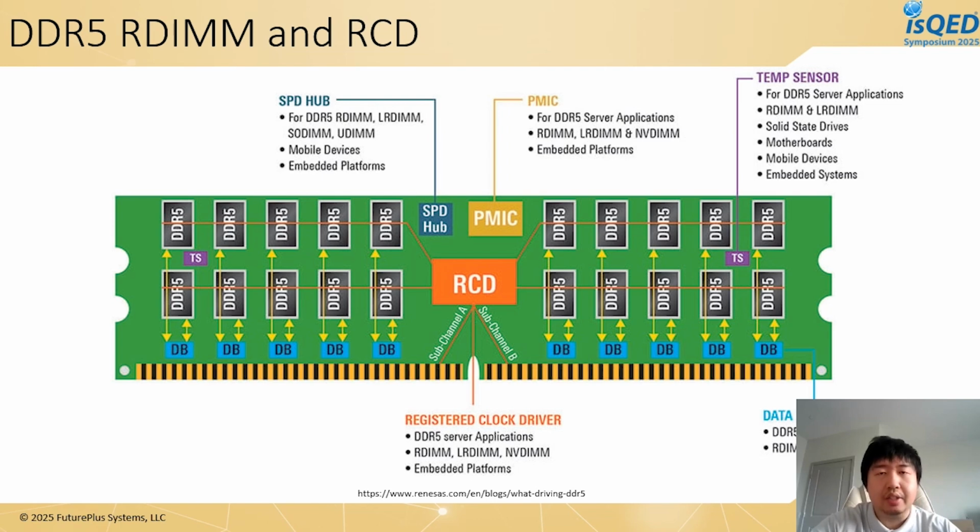So here is a block diagram for DDR5 RDIMM. Again, notice we have this RCD component on the center of the DIMM. Like mentioned before, it stands for registering clock driver. It takes the system clock and a double data rate DCA signal and converts them to 2 clocks for each subchannel of the RDIMM and a single data rate QCA data bus and feeds them into the DRAMs.